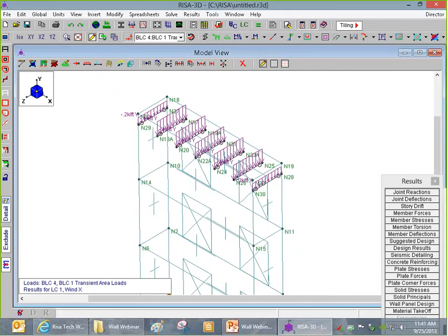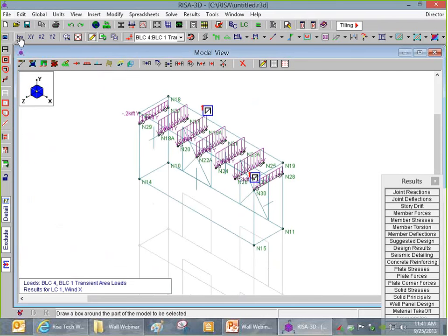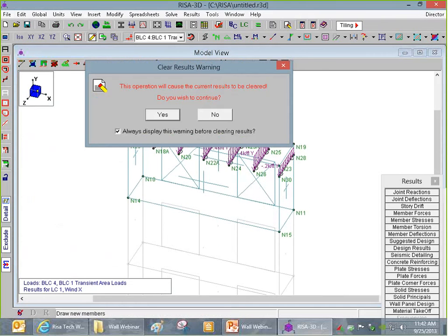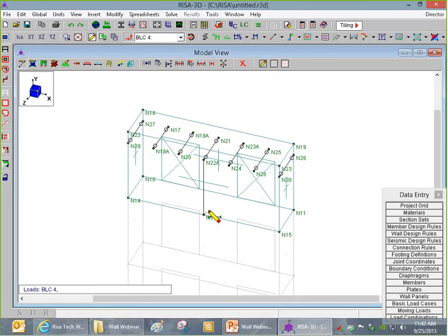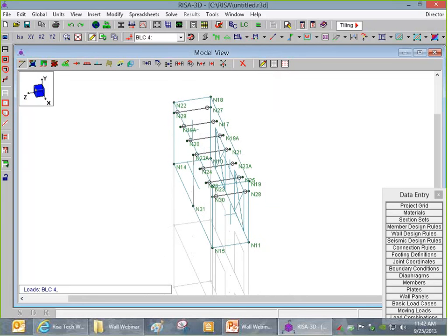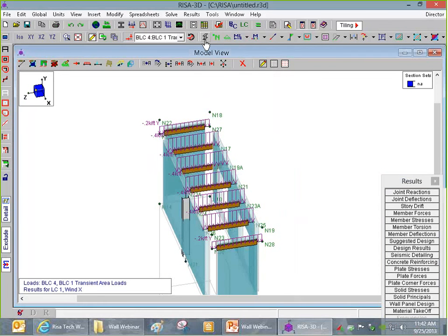Now, another thing to consider when you're talking about how walls and members interact with each other is how columns are impacted. So I'm going to come in here and draw a steel column. I'm going to pick out a W10x33 column in this case, and we will put this in as a fixed column made out of A992 steel and rotated 90 degrees. And what you'll see here is I'm going to draw this column being supported at the end of the beam there. And I'm just going to solve this model again. And let's just see how this looks.